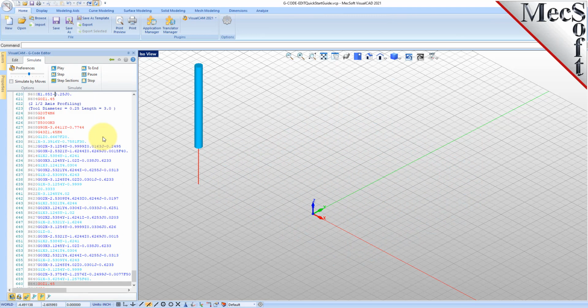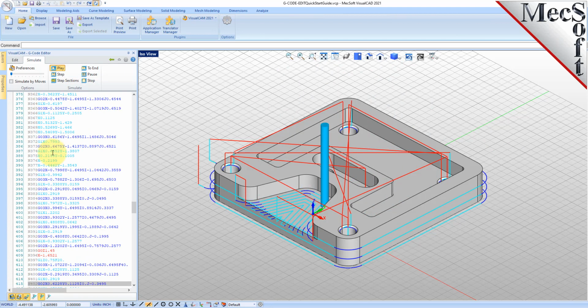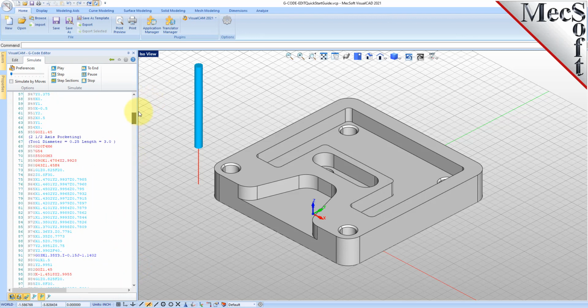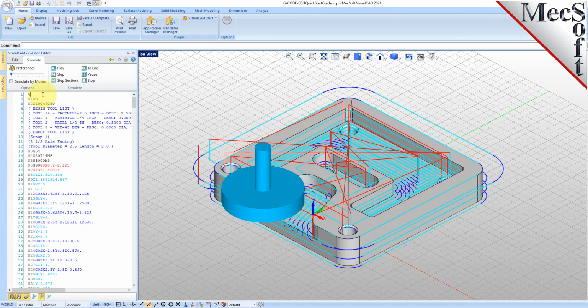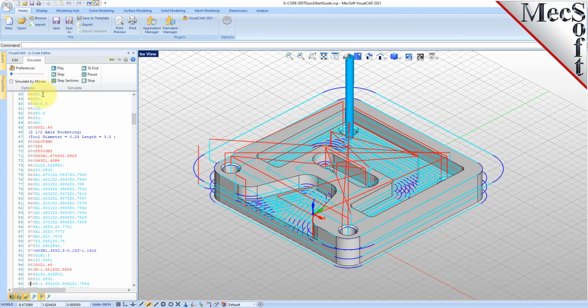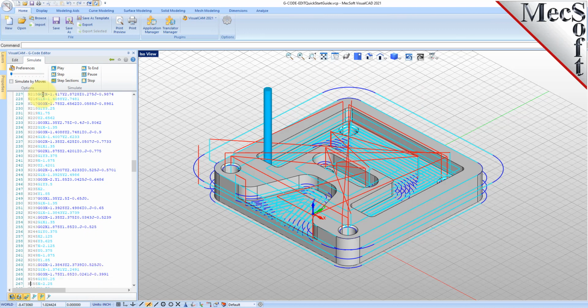And you'll see that the G-code is loaded into the editor, the Simulate tab is activated, and it's running through the G-code file, displaying the correct tool as it goes through each tool motion. Also, a cool thing to do is you don't have to run the entire simulation. You can just select a location in the G-code file and use the up and down arrow keys to show where the tool is located at that specific line of G-code. So this is a very good visual analysis, so to speak, of the tool motion itself as it navigates through the G-code file.